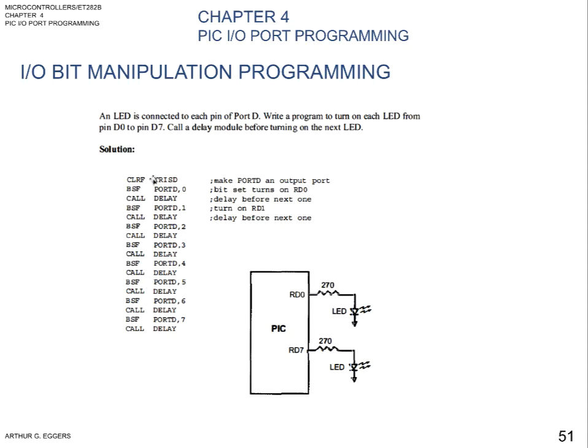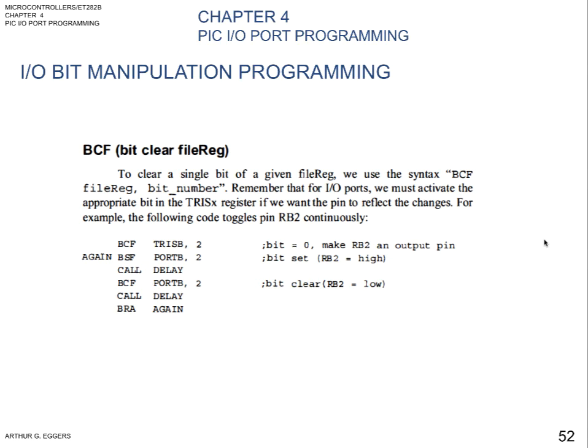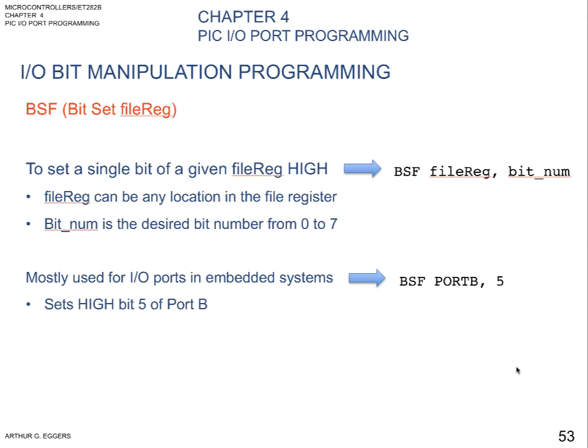Go ahead and enter this code into MPLAB and watch to see what happens using the watch window, because you will see the states change on each of the ports. Bit clear, again, the same thing is going on. Now instead of setting, we're clearing a particular bit.